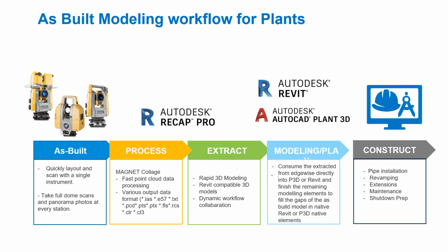Now, there are a lot of scanners available in the market from Faro, Topcon, Leica, etc. Depending upon the range and extent of these scanners, they are laid out on the construction site or layout where the scanned images or point cloud data needs to be extracted. So you typically take that layout and station your equipment in particular locations, and based on the range of your scanning equipment, it can take panoramic photographs and full dome scans of the complete layout, depending upon the size of that particular project.